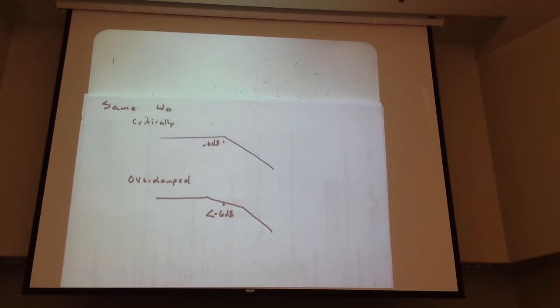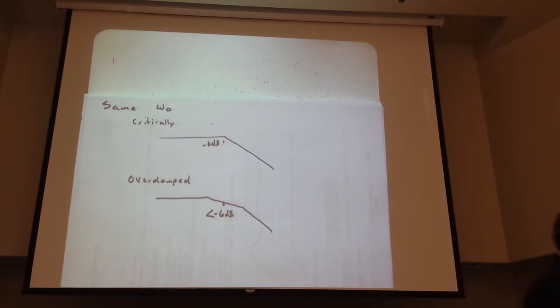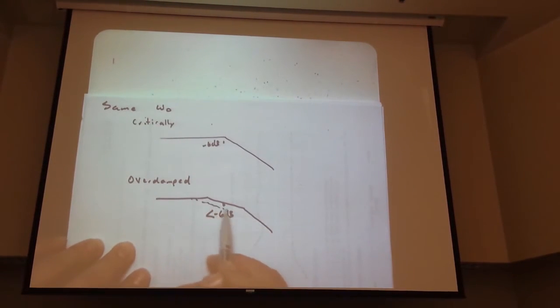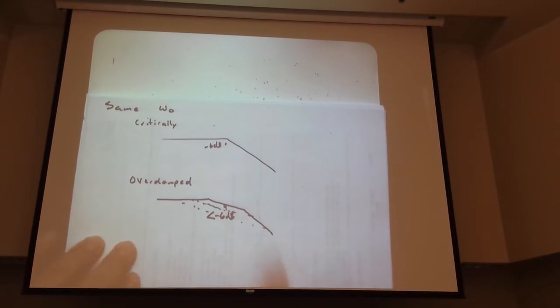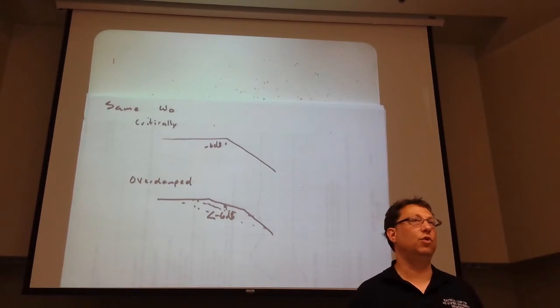It's the square root of the multiplied, which is halfway in between on dB scale. So if you think about it, as you spread this out, this point's moving down. You keep doing this. The asymptote here stays the same, and you introduce this 20 dB slope that's pushing that point down. But maintaining the same omega naught squared, that's important.